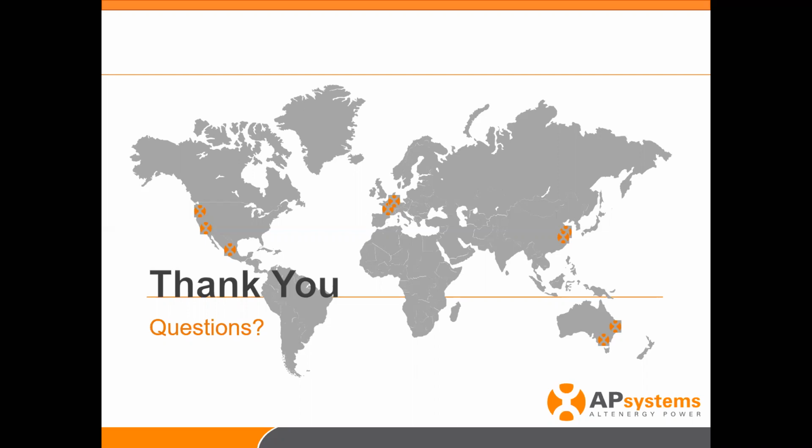If you go to gosolarcalifornia.com, this right here is also a great resource where you can look at all the modules that have been tested. It will show the manufacturer, the model, and the STC, or standard test conditions, that's printed on the label. Then it will also show their tested PTC. So that's a good way to get third-party verification.